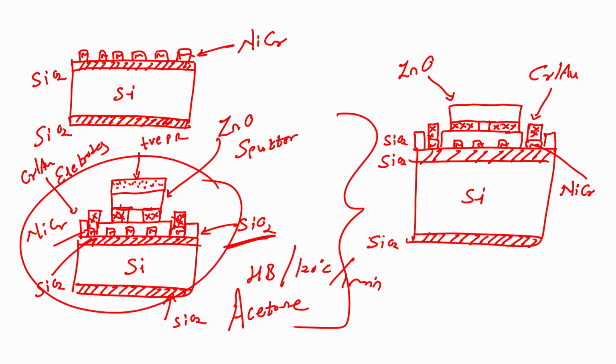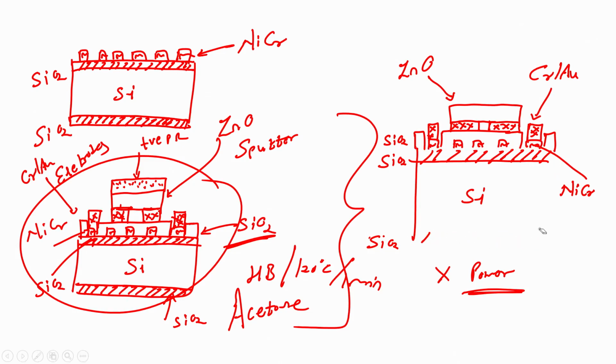Now, if you see, if I want to heat this particular silicon substrate, then I will require some x amount of power, right, x amount of power. If I want to reduce the power consumption for heating the silicon substrate, I can make a diaphragm. What does that mean? If I etch the silicon substrate with bulk micromachining, right, then now I have to heat, sorry for the design like this, okay. This is a little bit better than the earlier one.